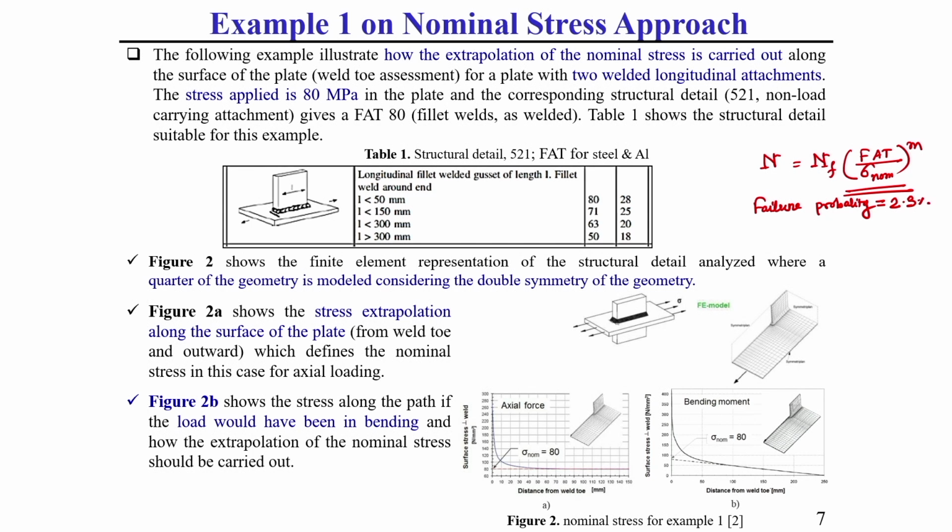If it is 2.3%, generally this probability factor phi is used inside this equation. Once the failure probability is 2.3%, the phi value becomes 1, this you should keep in mind. This illustration I will discuss here will be based on a failure probability of 2.3%, or alternately you can say a probability of survival of 97.7%. Another way to say it is that 100 minus 2.3 is the survival probability, this you should keep in mind.